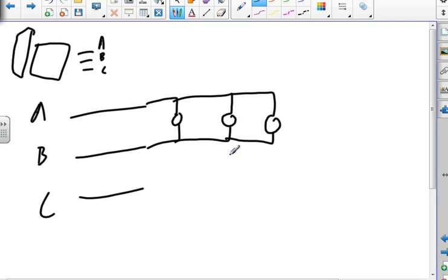So what happens is, and it's a subtle thing, I've got a motor that's connected Y, A, B, and C, and then I've got all my lights hooked up A and B. Well, now I'm drawing power A to B, and C isn't being drawn power.